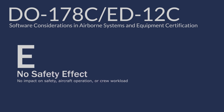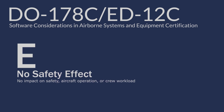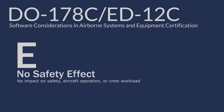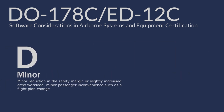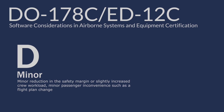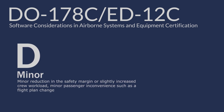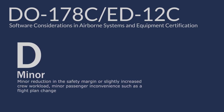The canonical example of a Level E system is an in-flight entertainment system. Though, if an entertainment system were integrated with the crew's public address system, it might actually need to be certified to Level D instead. Failure of a Level D system would cause some relatively benign effects, such as slightly reducing the aircraft's margin of safety or slightly increasing the crew's workload. Applications involving transponders, communication, and system maintenance have been certified to Level D.